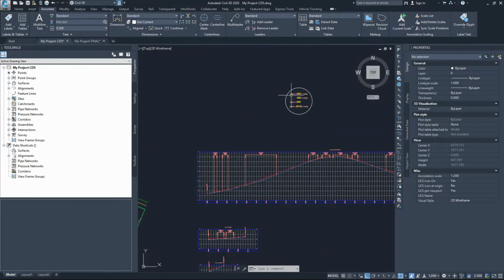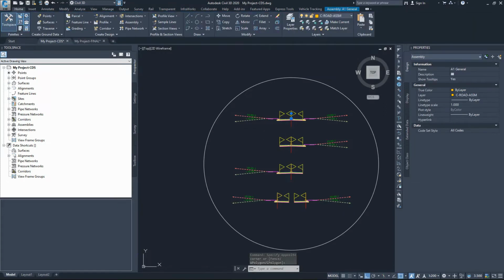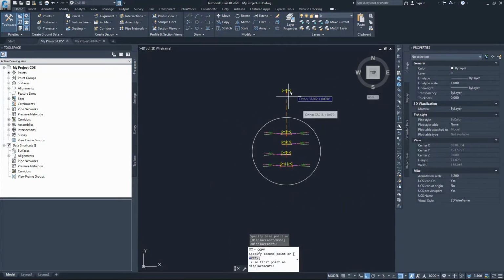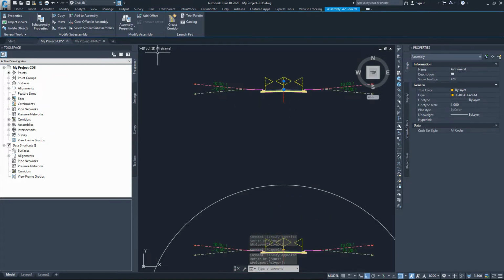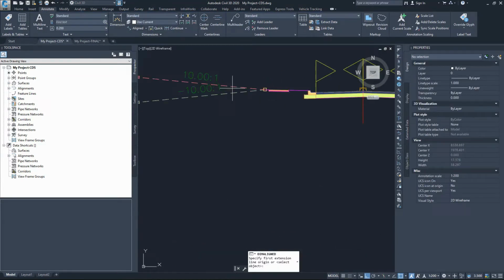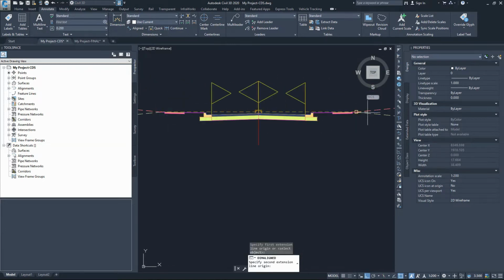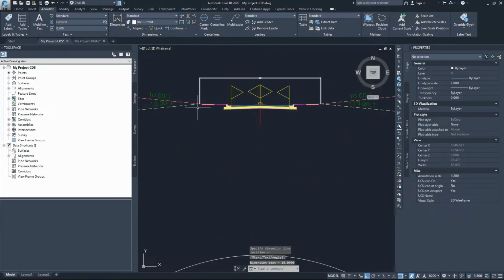So first of all, we have to create another cross section. So let's copy our main assembly. Go to copy. We'll call this one assembly 2, that one assembly 1. We work on everything, so let's call this one assembly 2 general, and let's start modifying assembly 2. First, we have to narrow this. This is 15 meters again. If I measure this assembly from outer boundary all the way to the other side, this is 15 meters wide. We have to make it 10 meters wide.